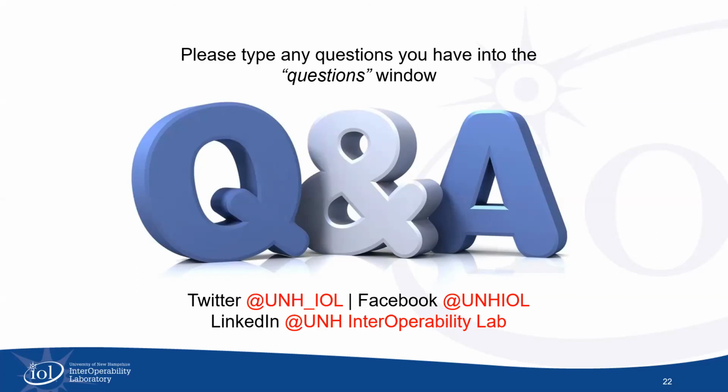And then, here's a good one for you, Blake. How long does it take to run a test with the QualiPhyer software? The amount of time it takes to run, say, an HS test is really dependent on the amount of information in the waveform data that the tool is given. However, in my experience performing C-PHY HSTX testing, it could take maybe a minute or two to produce results.